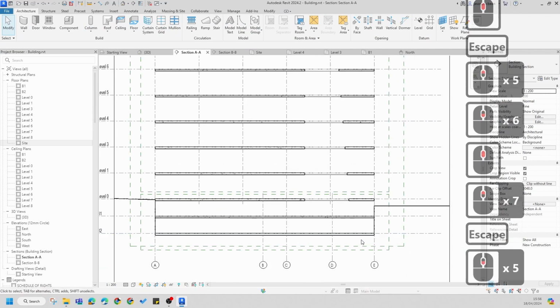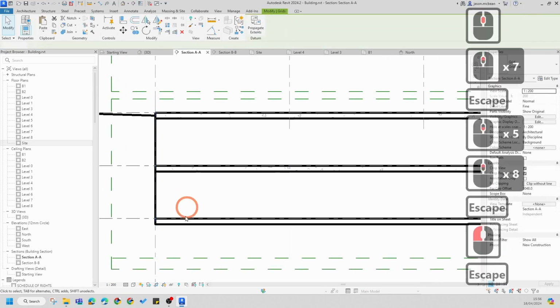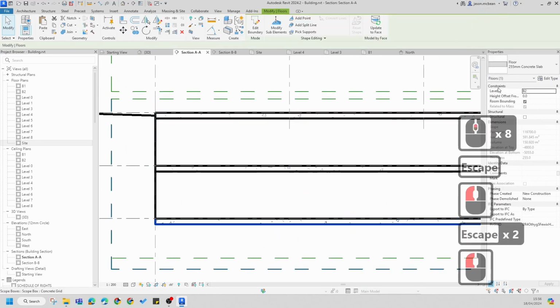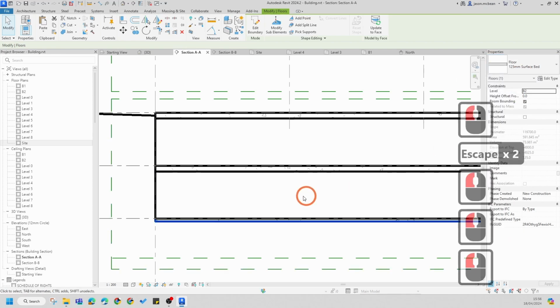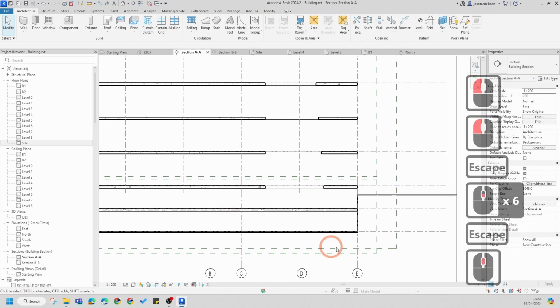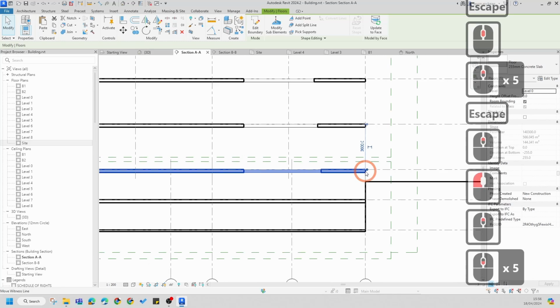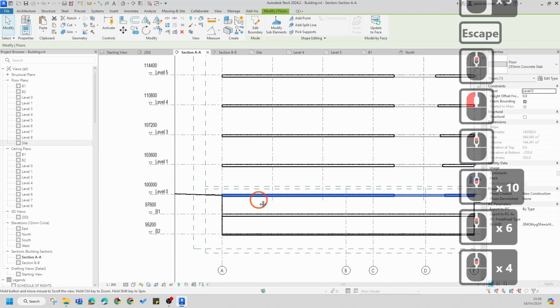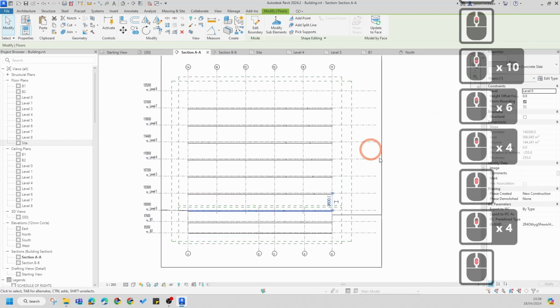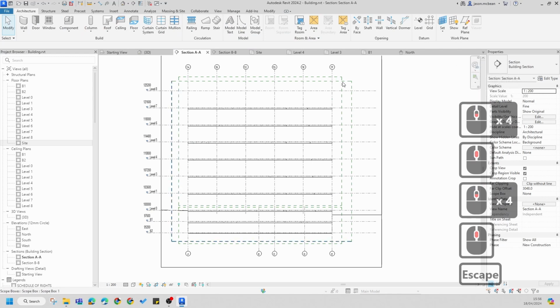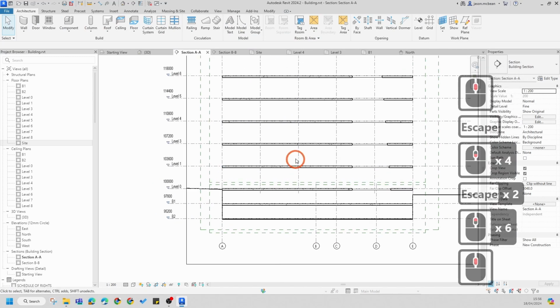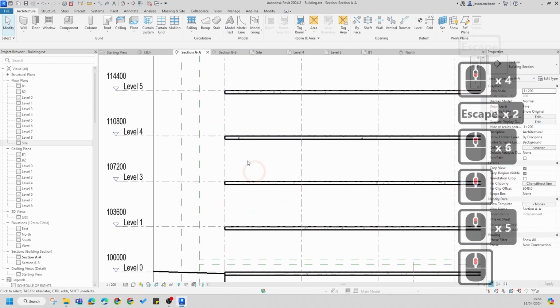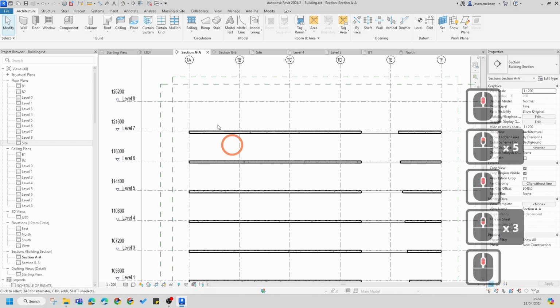And I can see here's my floor slab. Just remember, your ground floor slab is technically a surface bed. I'll get to that in a minute, so I've changed that. And this floor slab might be a lot thicker. Okay, so just remember that might have quite a large bearing on how things will work. But now, why do we want to draft a lot of information in the beginning? Because I'm going to pick a floor slab in here and I'm going to quickly explain what will start happening.